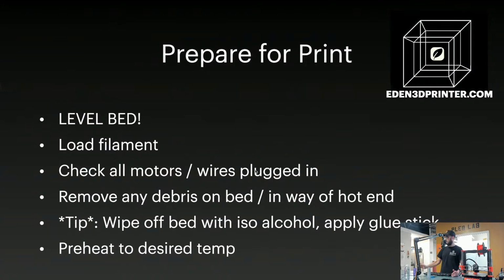So again, the most important thing there is obviously making sure your machine is calibrated properly. Level your bed. I cannot say it enough. Level your bed. Level your bed. Everybody say it with me. Level your bed. There we go. But it is one of the beginning problems, if not of almost all problems, when you're 3D printing.